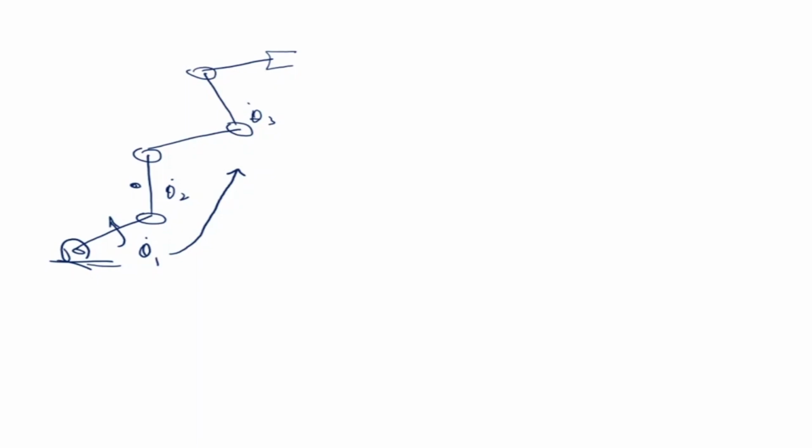Now let's look at the concept of static forces. We have looked at velocity propagation. Now let's look at force propagation. But something interesting is that both of them move in different directions. Suppose there is a force acting here. This force will cause a reaction force here, and this will cause a force here and here and here. So the forces are moving like this. From the top, the forces move backwards, and in the case of velocity, the velocities move forward. These are two interesting things about force propagation and velocity propagation.